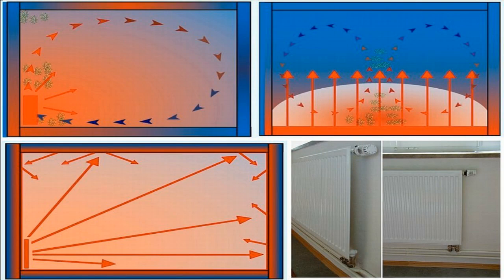A little to the heating. We see left above the convectional heating and right above the floor heating. Both heating systems will make a typhoon of dust in the room, and the dust will hurt for long and will make dirty the whole room. The idea is to have a better radiation and not so much convectional heating. So you see below the system of radiation heating and how we do it in the practice.